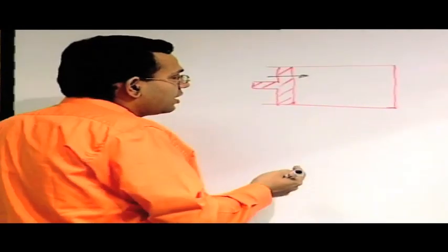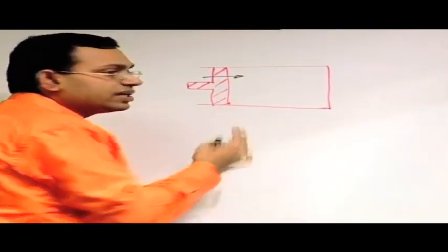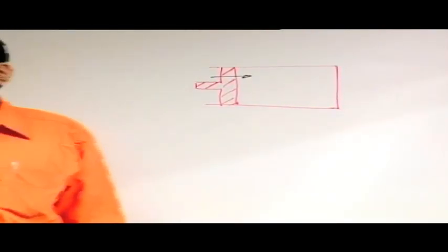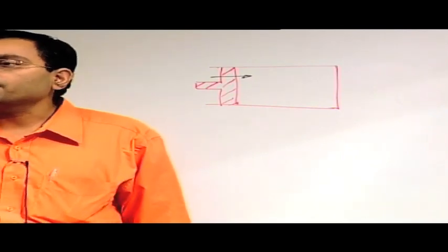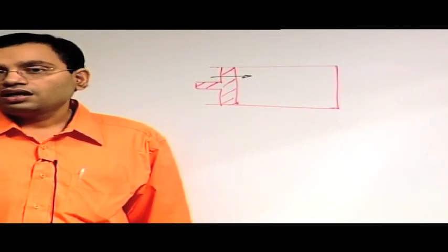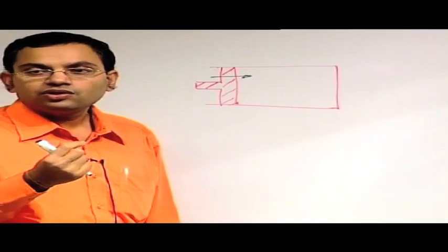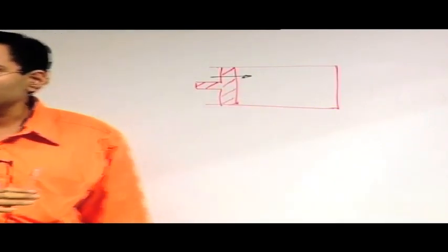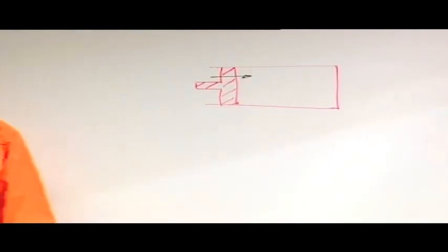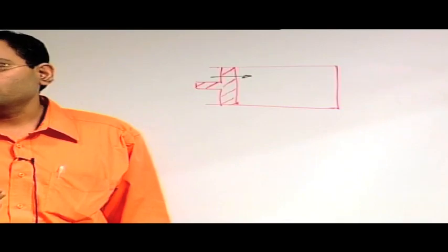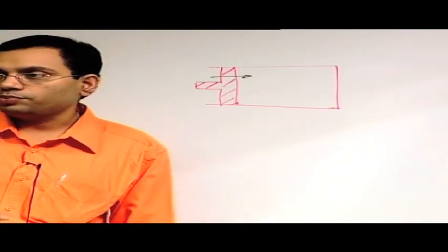So, the disturbance propagates through the medium at a finite speed, and if it is a weak pressure wave, it propagates at a speed which is a function of some of the properties of the medium, and one of our objectives will be to identify how it depends on those properties.